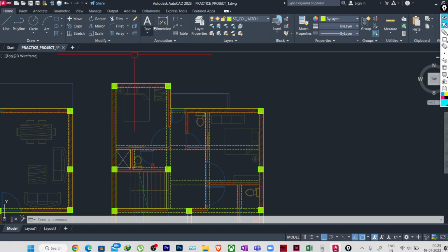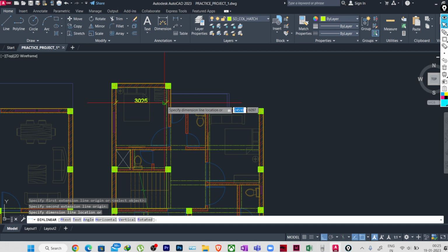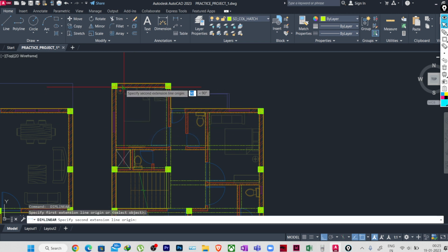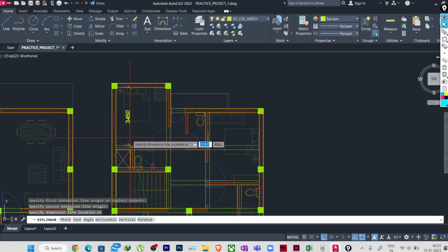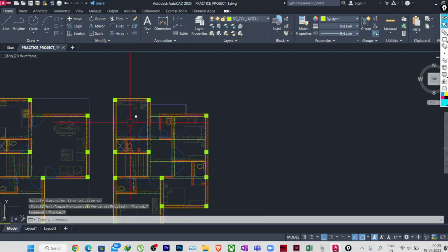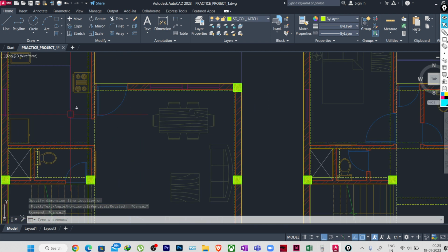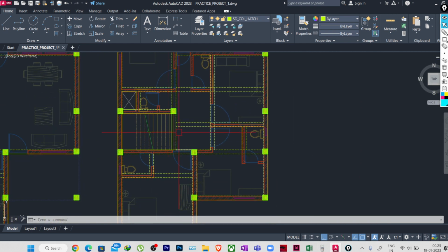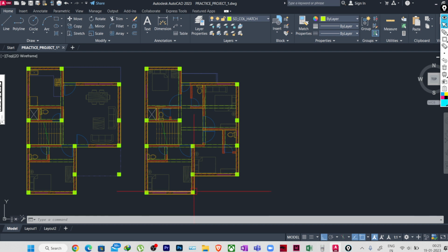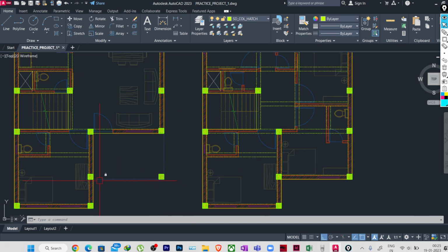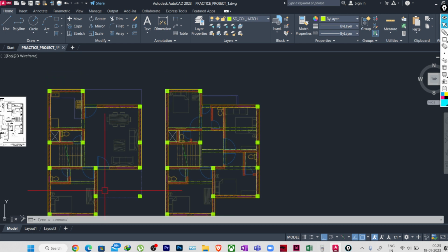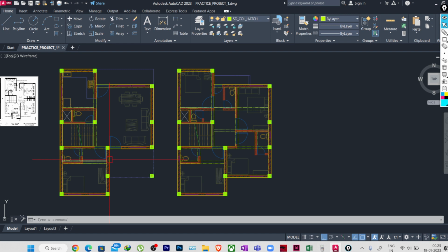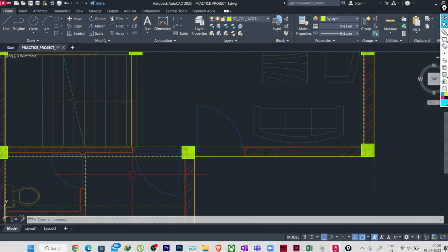I don't know, this panel maybe a bit bigger one, 3 meter by almost 3.5 meter. So if the deflection is not in control, you need to think about an alternative. For now I'm just going with this very basic plan. So you can see the beam column plan we have created. Now a few refinements we need to do.